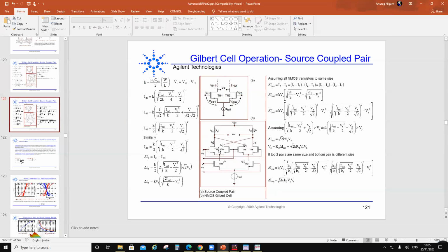So basically these transistors are no longer voltage controlled current sources. They are not operating in the linear region; they start operating like a switch. At that point, these TN3, TN4, TN5, TN6 are just doing current steering. They are no longer transistors as we see them as a gain stage, right?